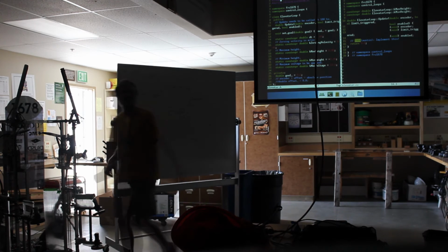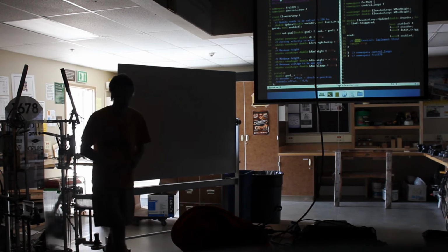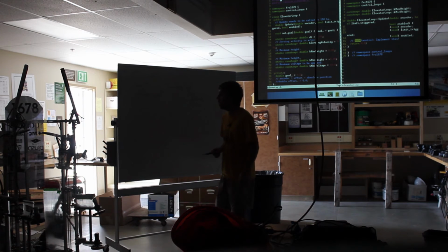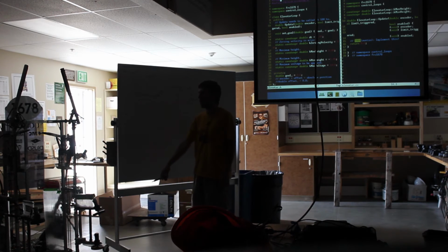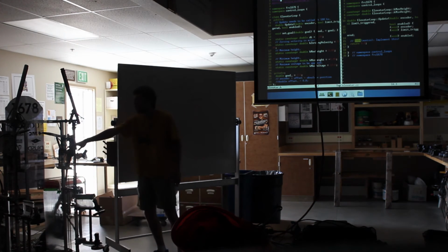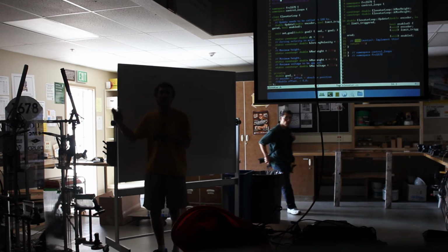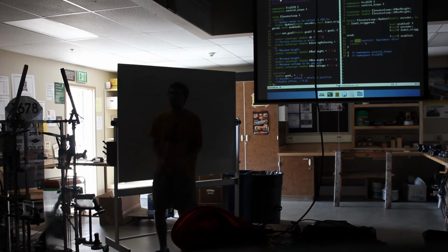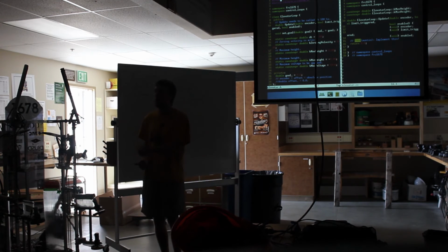But we'll see. So do we need to have a limit in there such that if it travels X distance, we know that it started below the Hall effect sensor, and we don't want it to overrun the bottom? I like to solve that mechanically, but you put the limit at the bottom rather than the middle. We can make this more complicated, but I think we should just ignore that and require the user to start it above. And then in a competition robot, I'd recommend putting maybe a second one down at the bottom, so you know if you went too low and didn't find it. Or you could have a timeout, where you've gone X and you didn't see it.